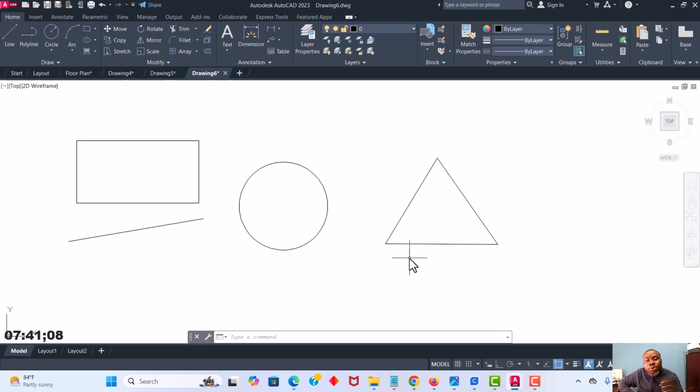The next thing you need to do now is to apply the setting. Very important notice: make sure the object snap is on. Before you can apply your dimension, be sure that object snap is on in your drawing aid. Object snap helps you to locate points accurately. You need to locate your endpoint accurately before you can apply your dimension. So be sure that this button is on.